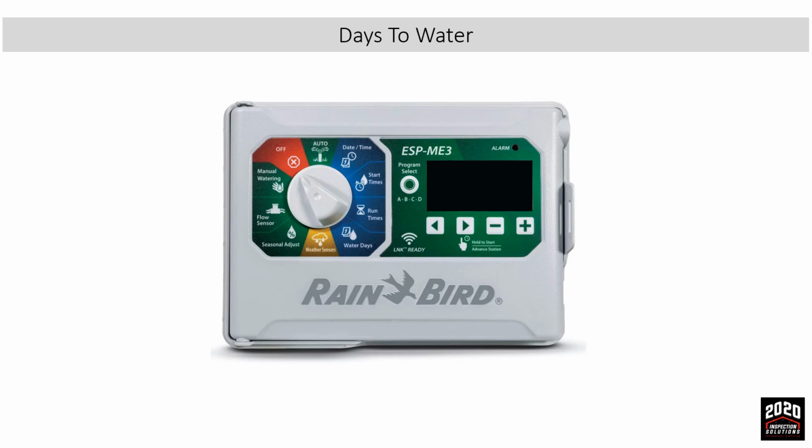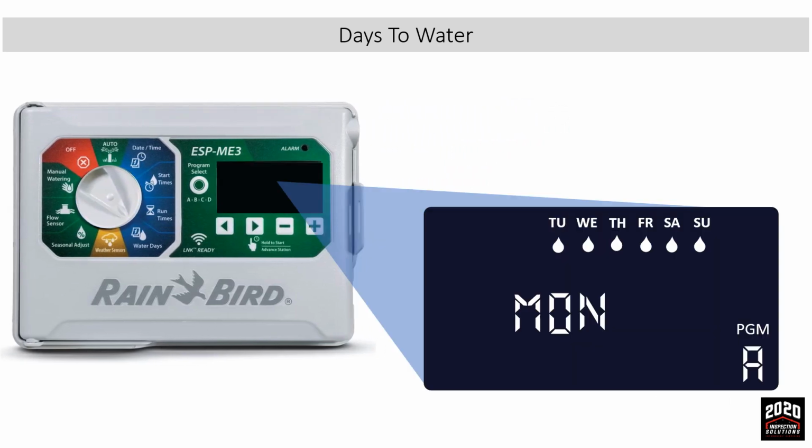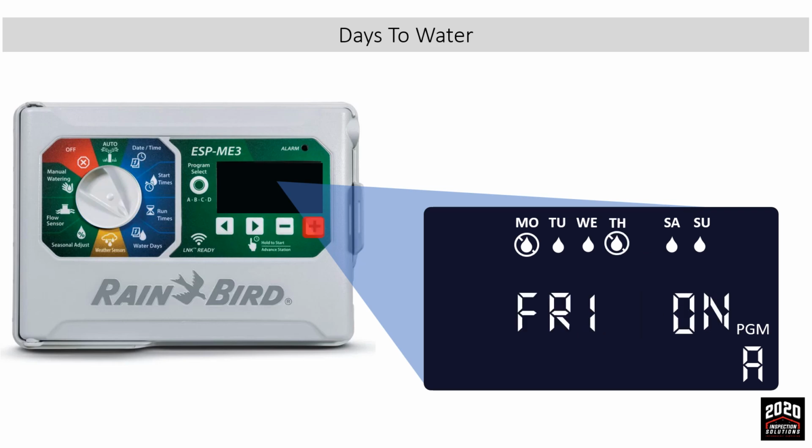Setting days to water. To set days to water, turn the dial to the days to water position. Now let's program it to water every day except Monday and Thursday. We'll press minus for Monday, plus for Tuesday and Wednesday. For Thursday, we'll use the minus. Then we'll use plus on Friday, plus on Saturday and plus on Sunday. You'll see that we only have a circle with a line through it on Monday and Thursday, which means no water.